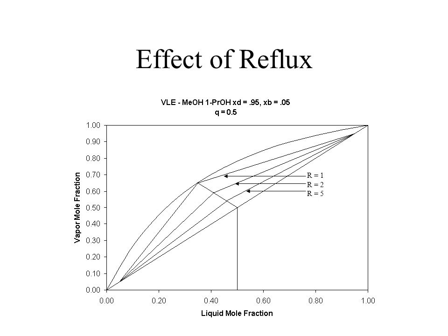Here we take a look at what we would get at different reflux ratios. Again, we would have a feed coming in at 0.5. In this case, my Q is 0.5, so it's halfway between a liquid at its bubble point and a vapor at its dew point temperature.